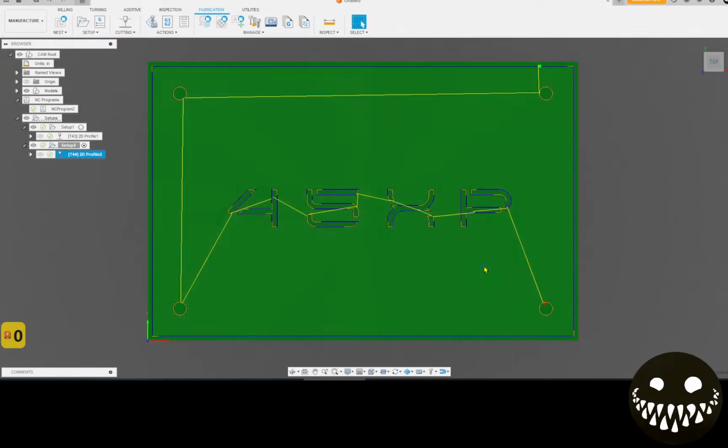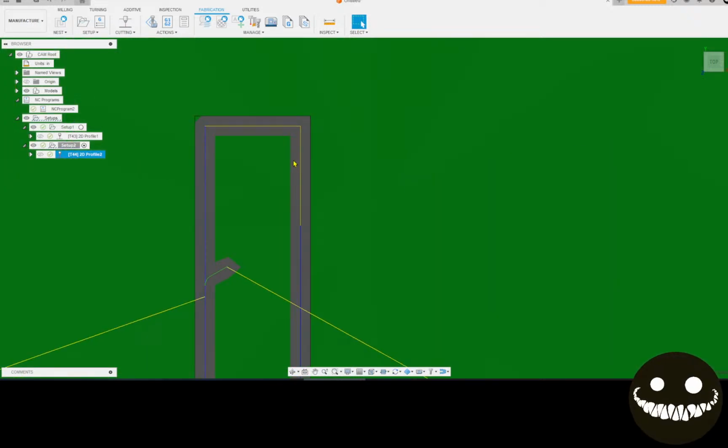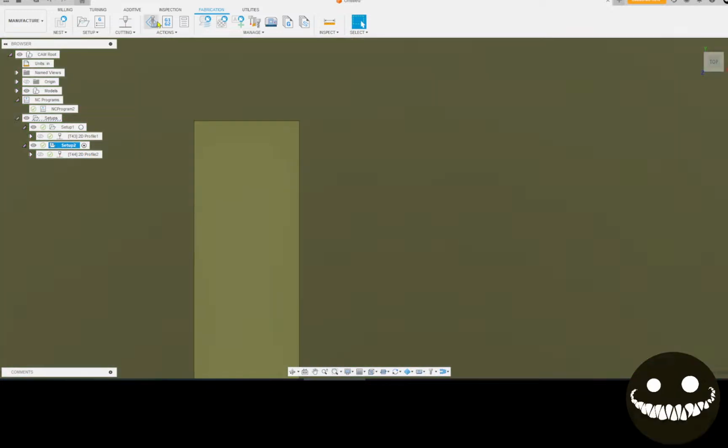All right, now we've developed this new toolpath for cutting it out of 14 gauge. So it's basically the exact same toolpath. It's just running a little bit faster. Yeah, I could have picked a better example where they do have different cut heights, or they do have a different kerf width too, which means that this line where the cutting happens is going to be put at a different width away from the actual cut line, because the kerf width is different in the 14 gauge than it is in the 1/4 inch, which means that this line should be closer to the actual cut line. So we'll go in here and just watch this simulation again.